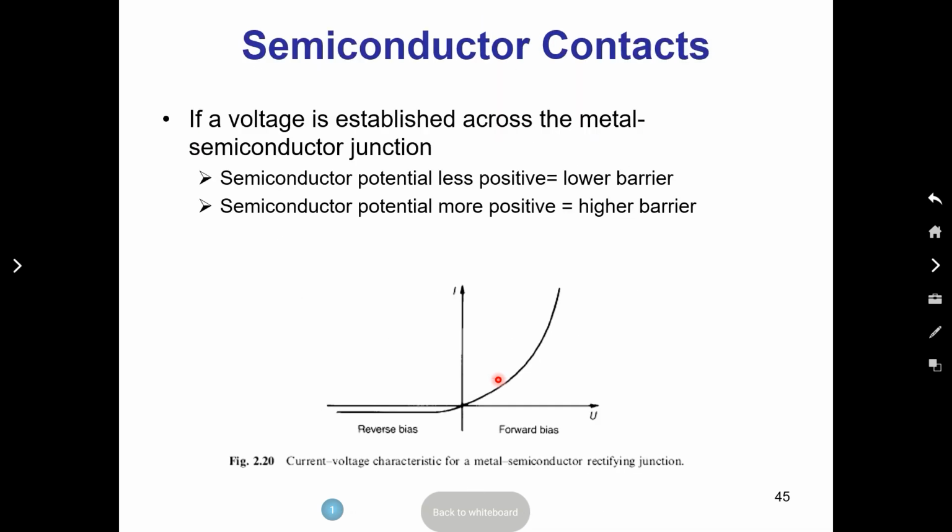For electrical conductivity measurement, we want to use a metal whose work function is smaller than the Fermi energy. So the band bending would be downward. So at the contact, it will be a downhill flow. There is no extra barrier.